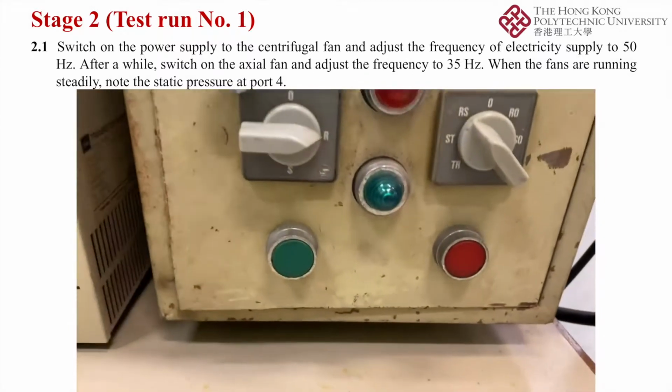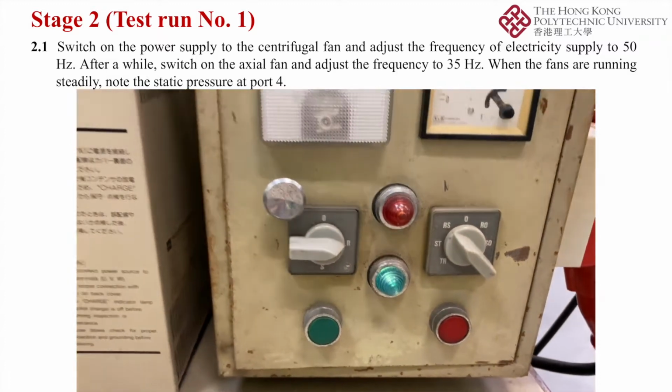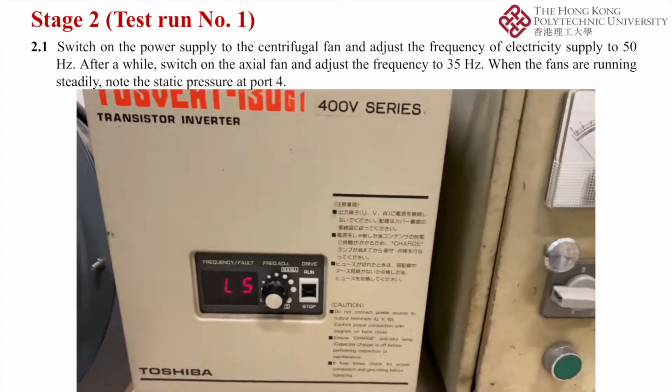After a while, switch on the axial fan and adjust its frequency to 35 Hz.